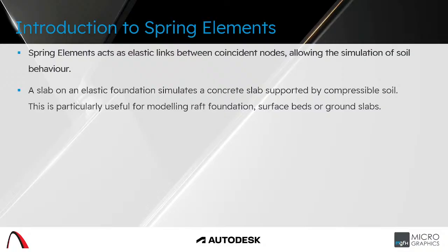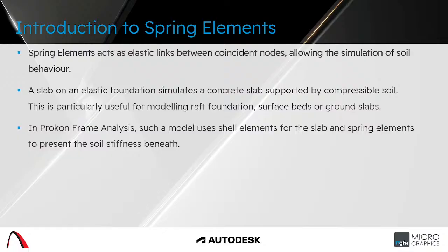This is particularly useful for modeling a raft foundation, either surface beds or ground slabs. And then within Prokon frame analysis, such models use shell elements to build your slab. And then from there, we use spring elements to represent the soil stiffness beneath the slab.